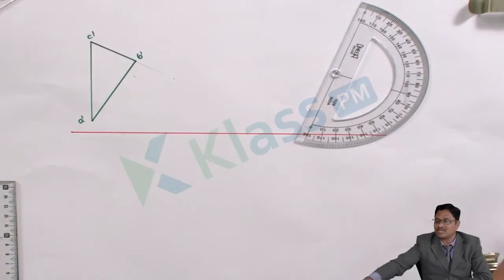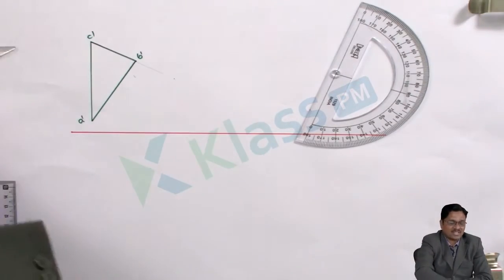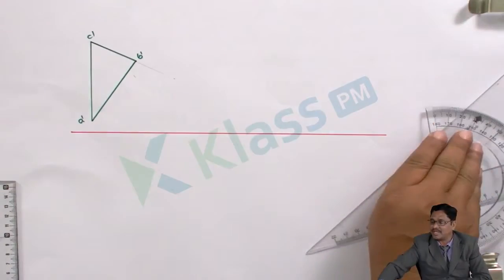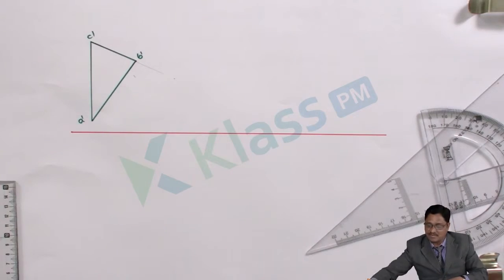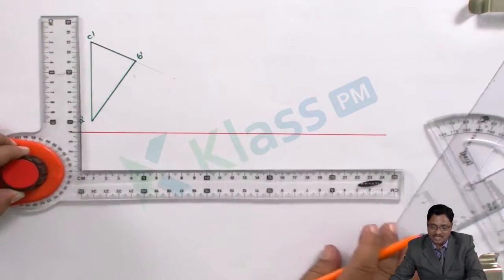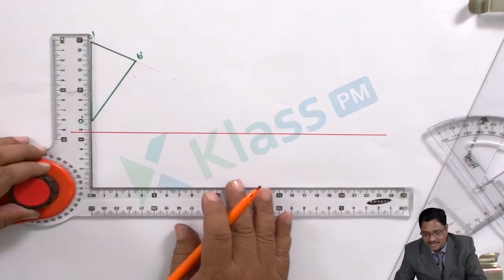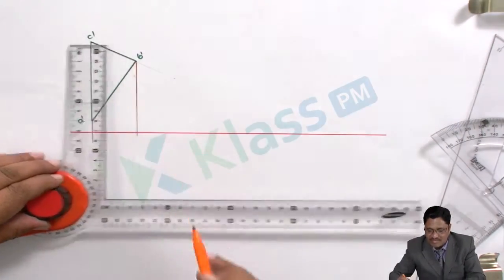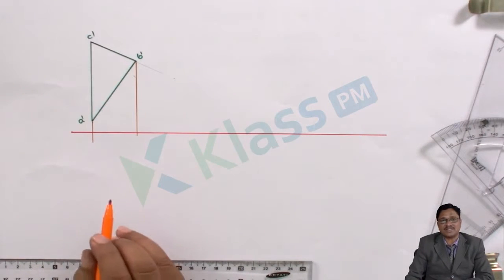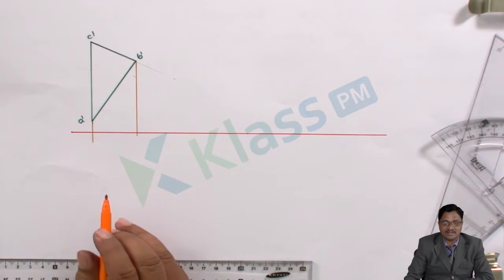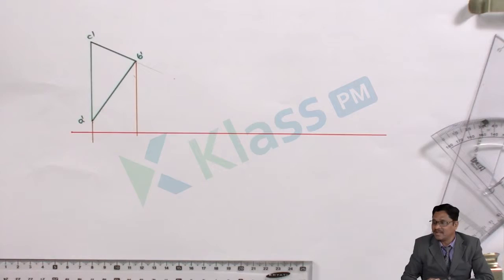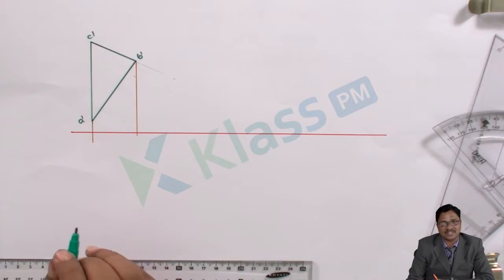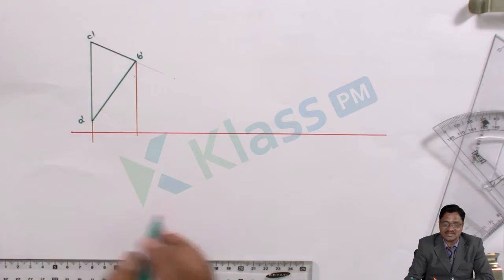The respective top view is to be drawn by considering the same concept: front view and top view in the same line. So take your mini drafter with the help of the 2H pencil and draw the projection lines onto the other end. Now identify the condition. The edge is in the VP. The top view gives the details of the vertical plane. Clearly they mentioned the edge is in the VP, which means there is no distance. It should be aligned at the primary condition along the line.